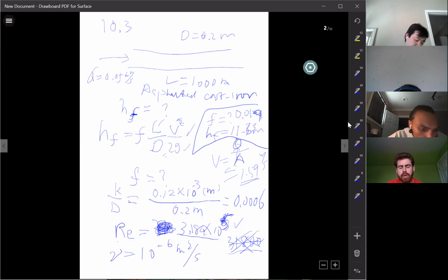Why do we not use the second term in the head loss equation, the k times v squared over 2g? You don't have minor loss in this problem. I thought you said both those terms were for head loss. Yes, it is for head loss, but in some situations you don't have those terms. If you don't have a fitting, a valve on there, for example, then you don't have that term. The second term with K is for those components attached to the piping system.